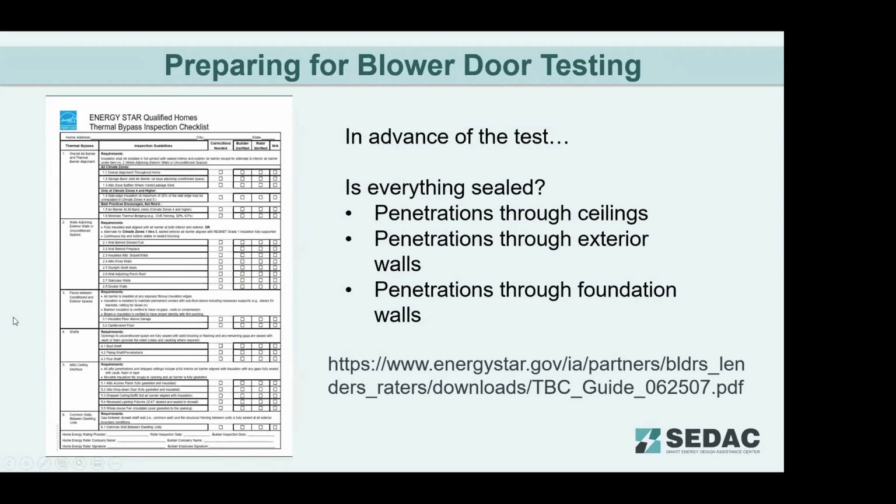So, preparing the building for the blower door test. Well, the big question from the builder's perspective is: has everything been sealed? Have the penetrations through the ceilings been sealed? Have the penetrations through the exterior walls been sealed? Penetrations through foundation walls? Sometimes this is simply some caulk or some can foam. Sometimes it's a little more complicated.